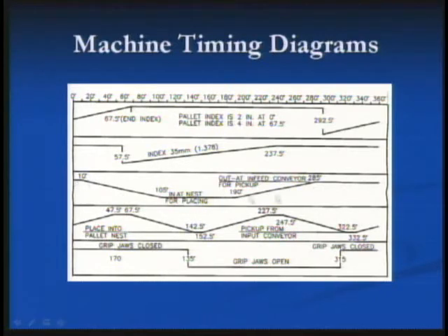Even though it looks like there are 3 dwells, this is just the tail end of this same high dwell over here. So it's dwell, fall, dwell, rise, back onto the dwell. This one down here apparently is a double motion, twice per cycle. 360 degrees would be a complete machine cycle. So this is in the middle of a rise at what's termed machine 0, which is just a reference point for all events in the machine when you consider the cycle to start.